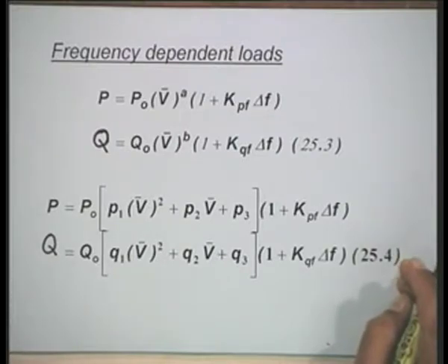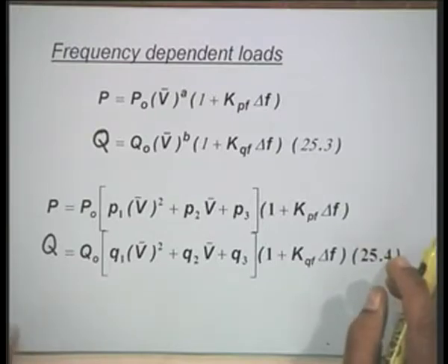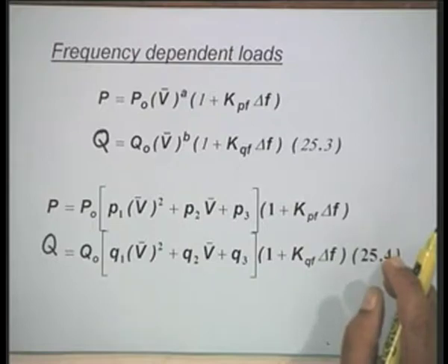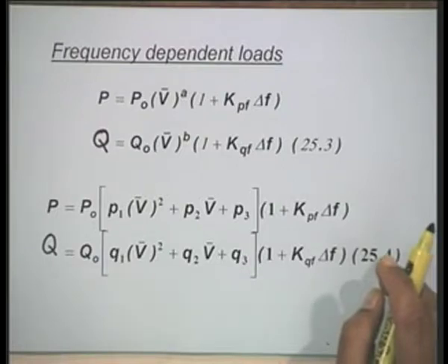The next important aspect of static load modeling is the frequency dependency of loads. This is a very important aspect of load modeling, that is the loads depend on the system frequency. In most of the cases the real power consumed by the load increases when frequency increases, and real power consumed by the load decreases when frequency decreases.